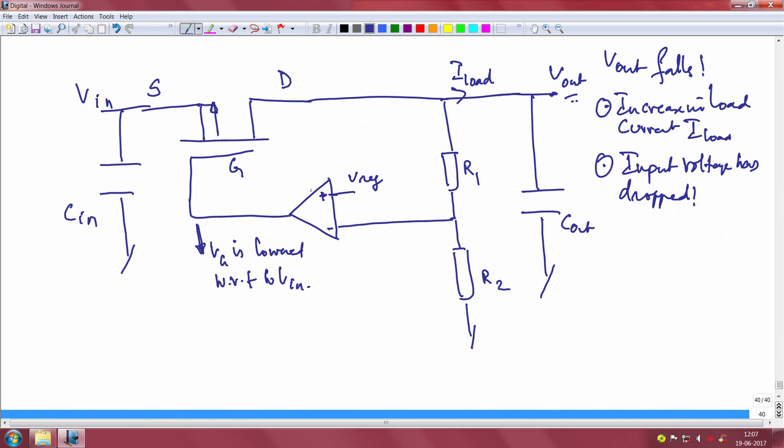You would have had a charge pump here or a V bias which is fed from outside. Recall you had a point here which essentially was connected. I will just draw it in dotted line so that you do not get confused. This was either a charge pump slash V bias, which was connected in the case of an N channel MOSFET, but in P channel you do not have to worry about that.